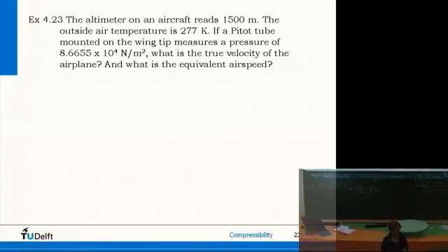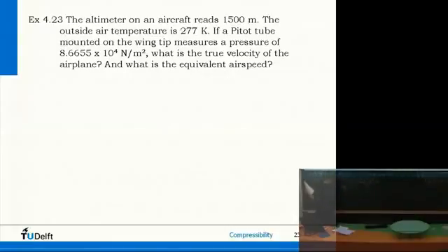And why is the temperature given here? Temperature is much easier to measure. How do you measure densities? It's very hard, but temperatures are always monitored, so always measured. So the temperature is given, so we find rho from the equation of state. So rho is P over RT. The pressure is given there. So please be aware which pressure you use.